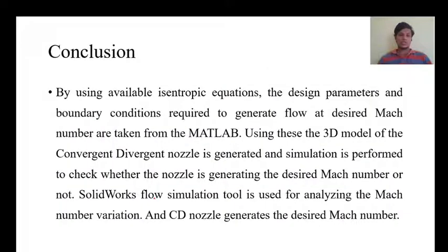Going to the conclusion, we have seen the MATLAB program and the MATLAB graphical user interface, and the inputs we have given to the MATLAB program, and the boundary conditions and geometrical parameters given by the graphical user interface. Those boundary conditions and geometrical parameters are applied to the flow simulation model and geometry of the nozzle, and again it gives correct or approximate results, that is Mach 3. We have given Mach 3 as the input to the graphical user interface, and hence it generated output as a Mach 3 nozzle from the flow simulation.